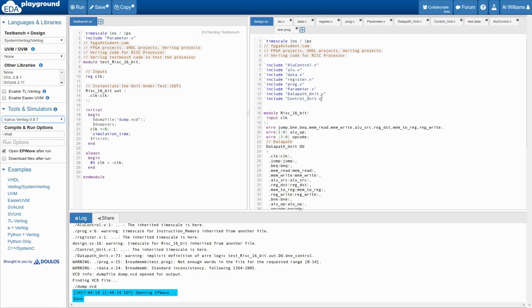Now, the way the thing came off the website, there's a couple of things in here that really wouldn't synthesize well. There's some initialization that's really pretty much just for simulation, and that includes some data files that I'll show you in a minute that wouldn't actually synthesize down to FPGA. So if you wanted to really put this on an FPGA board, it would be a little extra work. Nothing too hard, but it would be extra. But in theory, this is all the stuff that would go over to the FPGA.